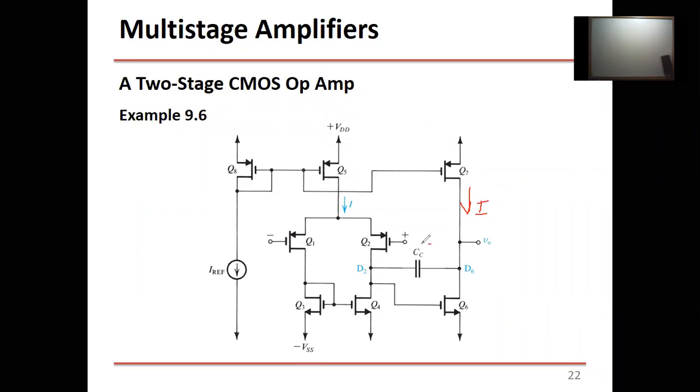Okay, this capacitor is called compensation. This is not out of our scope, but this is something for compensation. We'll talk about it later on. But see, this is why we say it's two stages. Where are these two stages? The first one is the differential pair, PMOSFET, using a current mirror as the tail current, using a current mirror as an active load. And instead of RS and RS, we use the transistors. And then the output of this first stage is connected to a common source stage with an active load of another current mirror from Q8 and Q7, okay?